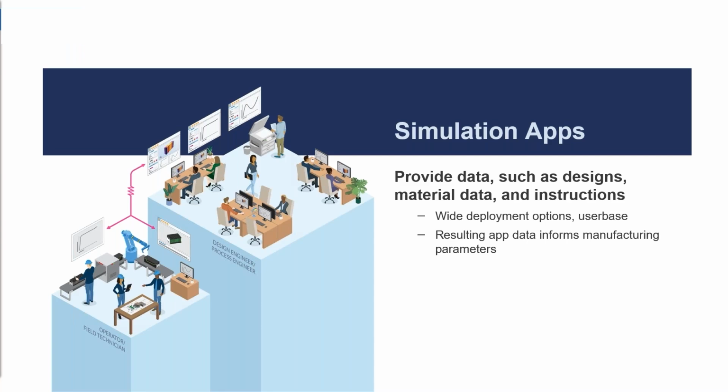There's a lot of deployment options. You can actually compile them. We have the Comsol Compiler, so you can package this up into an executable and then give it to anyone who needs it, and then they can go ahead and run that simulation anywhere. They don't even need to know that Comsol's under the hood. You don't even need to have a Comsol license when you're using the compiler. You can also have a server that's running remotely. If maybe somebody's working on a tablet or a desktop, they could input devices, send it to the cloud, run the simulation, and get the results back.